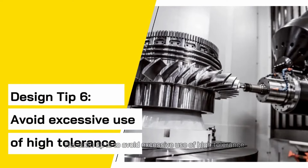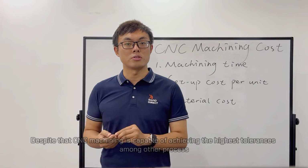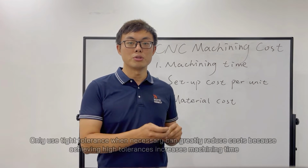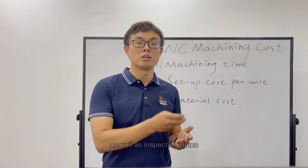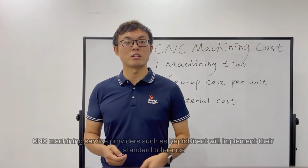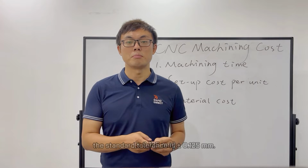The sixth tip is to avoid excessive use of high tolerance. Despite that CNC machining is capable of achieving the highest tolerances among other processes, it doesn't mean that every part requires the highest tolerance. Only using high tolerance when necessary can greatly reduce costs because achieving high tolerance increases machining time as well as inspection time. If a part is submitted without specified tolerance, CNC machining service providers such as RapidDirect will implement their standard tolerance. Here at RapidDirect, the standard tolerance is plus minus 0.125 mm.